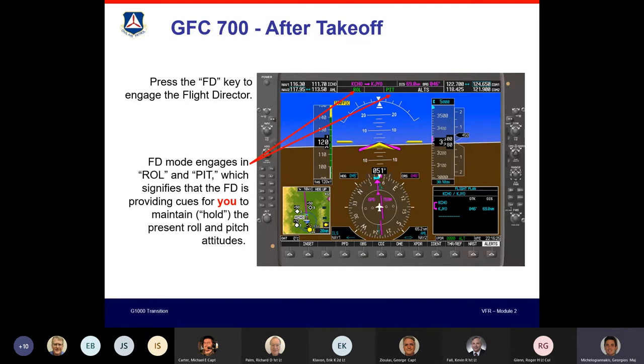Okay, all right, and part of your Form 5 is also to demonstrate that it's a mandatory item. What happens in a runaway trim situation? The first thing the checklist says is firm grasp of the yoke. So basically, don't let the plane climb or descend, whatever it wants to do. You'll notice that you actually have to push hard. You have to exert force. And then do the rest of the items, which is press the disconnect button, change the trim, and then the breaker, if I remember right.